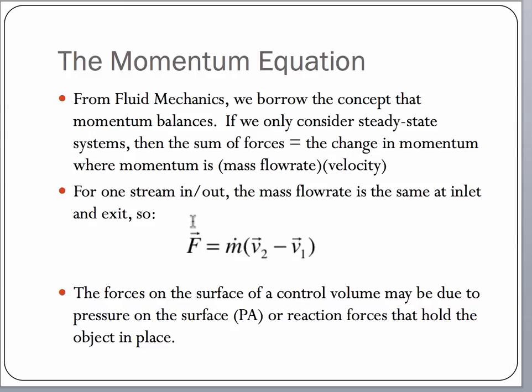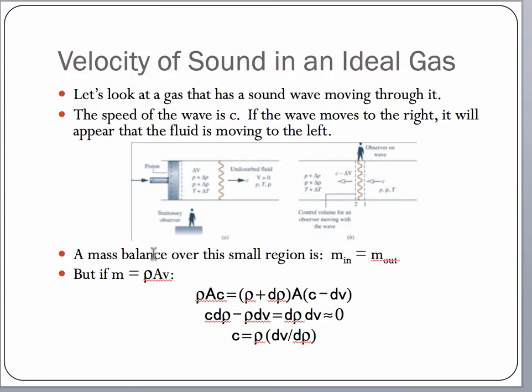And those forces are going to be either due to whatever reaction forces are holding my object in place or due to pressure on the surface. So now let's look at a gas. We've got here like a piston and cylinder, and we're just going to pump that little piston just slightly. That's going to change the pressure. It's going to just start that stuff moving. And what's going to happen is a little bitty wave will form, and it will move across the fluid.